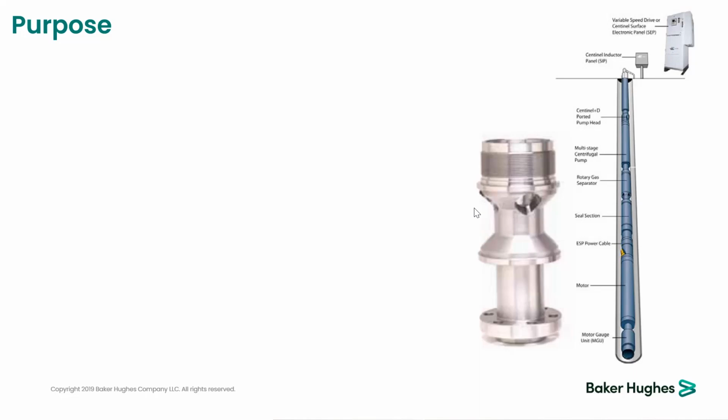The next question: is it normal to see signs of down thrust on the stages, or a missing or damaged washer, in a pulled-out compression pump? If not, what could be the reason? For a compression pump, you shouldn't see a severe effect on the thrust washer.